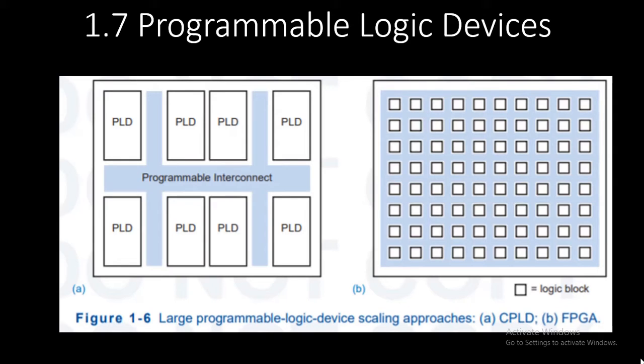Also important in achieving short time to market for all kinds of PLD-based products is the use of HDLs in their design. Languages like ABEL and VHDL, and their accompanying software tools, allow a design to be compiled, synthesized, and downloaded into a PLD, CPLD, or FPGA literally in minutes. The power of highly structured, hierarchical languages like VHDL is especially important in helping designers utilize the hundreds of thousands or millions of gates that are provided in the largest CPLDs and FPGAs.